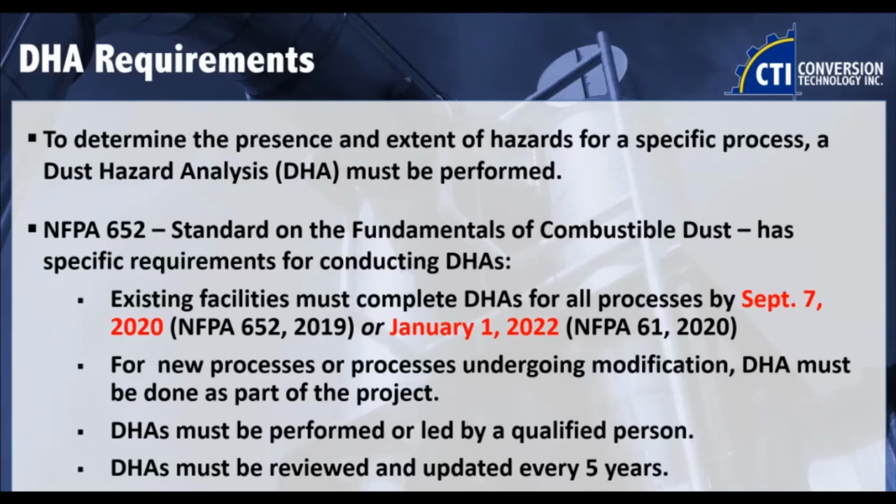the DHA's main requirement is to determine the presence and extent of hazards for a specific process. So you can do a DHA of your whole facility, that's kind of the point, but your DHA is looking at your specific process, specific equipment with the specific material you have, with specific safeguards you use. And then, I keep using bucket elevators. That's just the article I'm currently writing about.